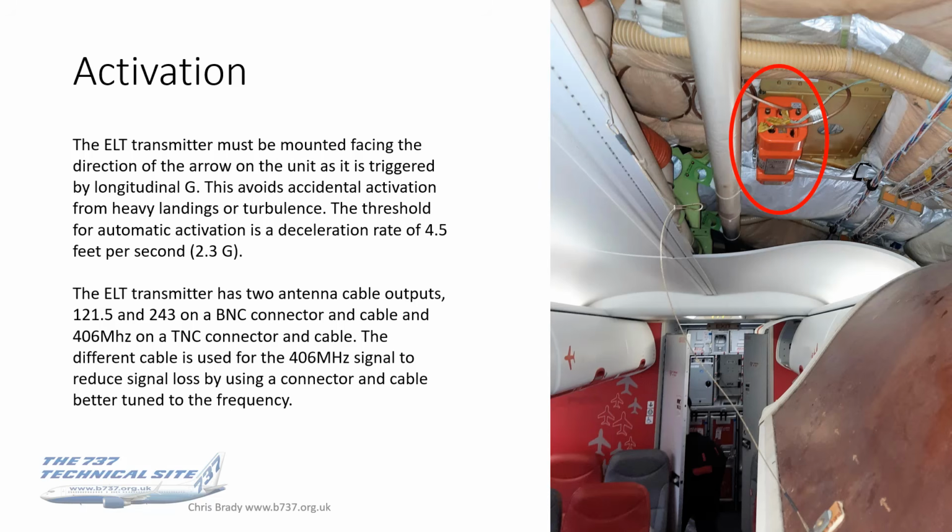Interestingly, it must be mounted facing the direction of the arrow on it. You'll see in the next photograph that there's a sort of this-way-forward arrow on it, and that's because it's triggered by longitudinal G. This avoids accidental activation from heavy landings or turbulence.